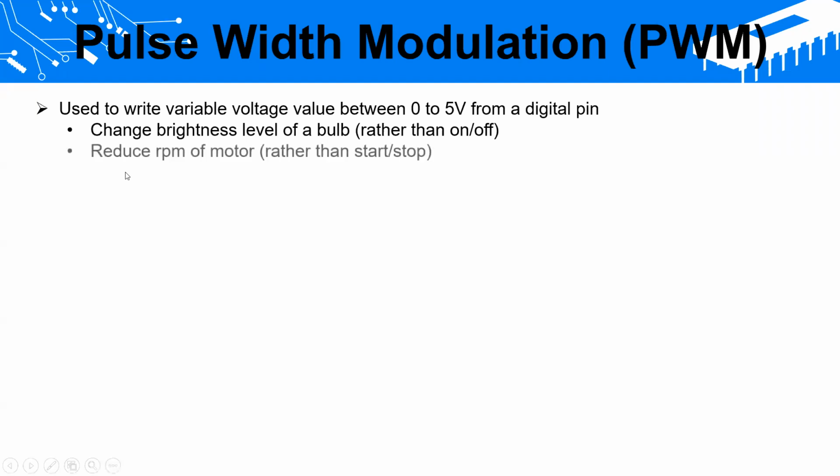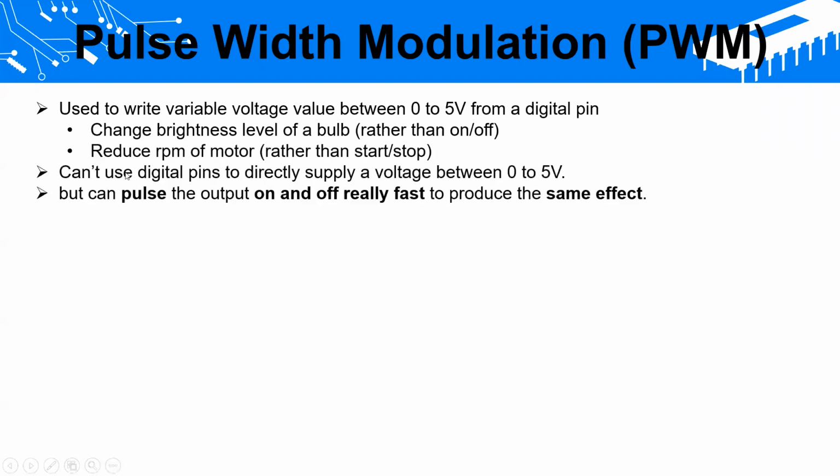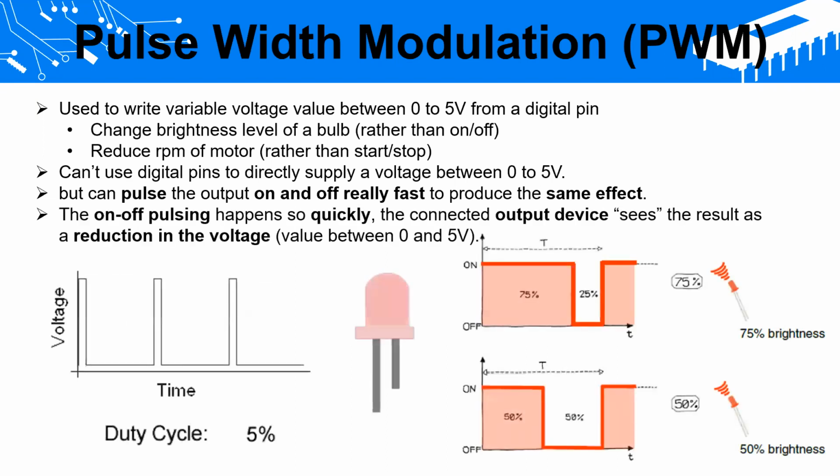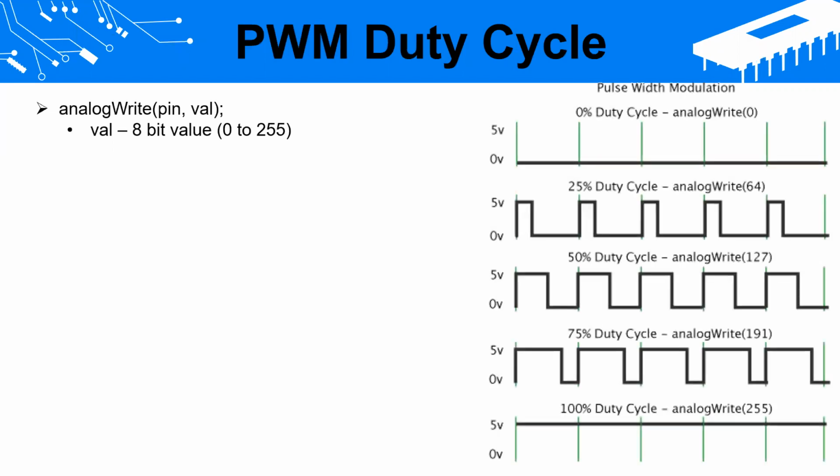It's a kind of tricky thing. Since we have a clock of 16 megahertz, by using this clock we basically give pulses. We can give either 0 or 5, either continuous 0 or continuous 5. So what we do is give small time durations. We give like 100 milliseconds for 5 volts, and the rest of the time will be 0. Like that, we are giving pulse signals.